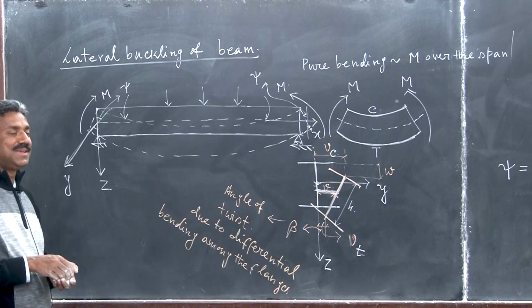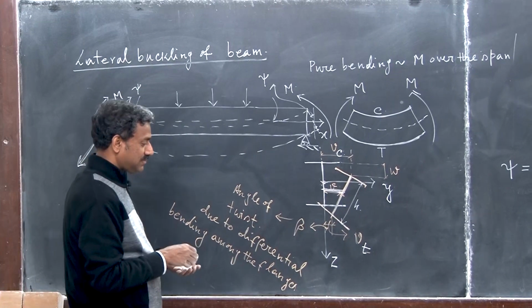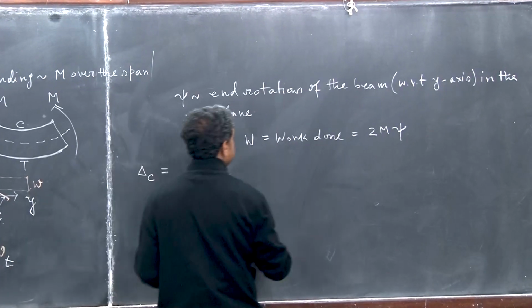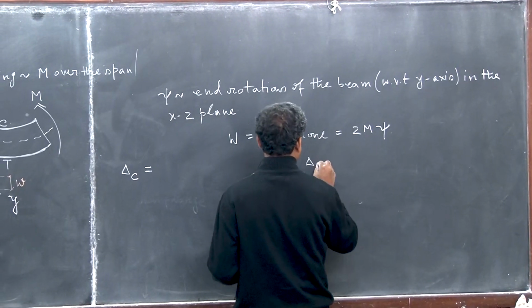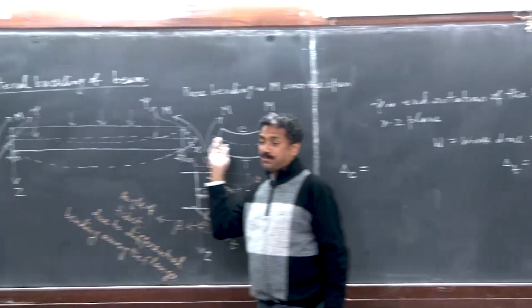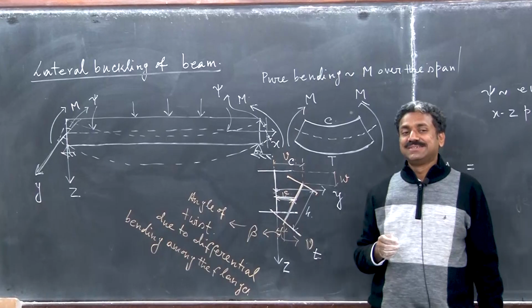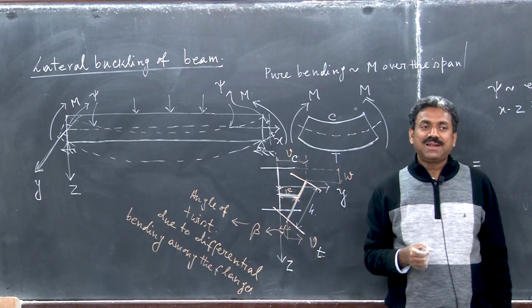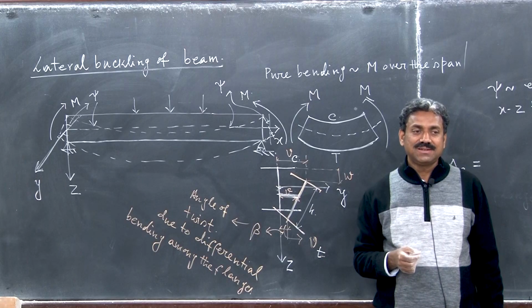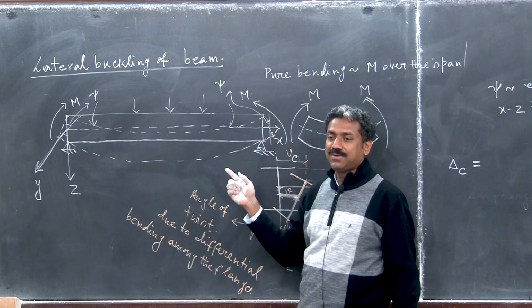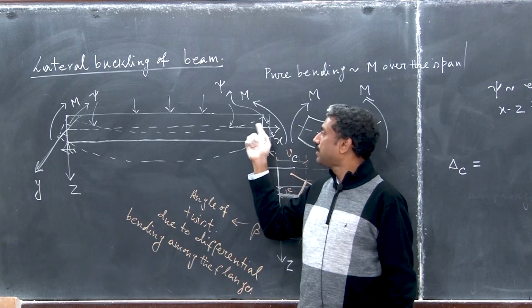See what is happening. This beam is going to be subject to out of plane deflection, right. So, what is the in plane displacement because of out of plane deflection? When it is laterally deflecting in the xz plane, what is the deformation along x?